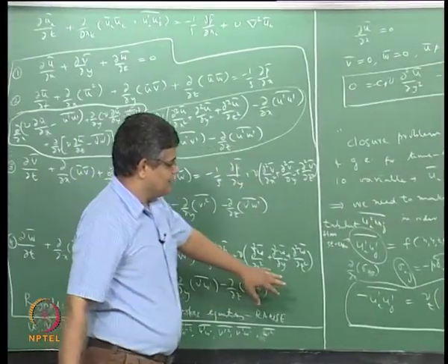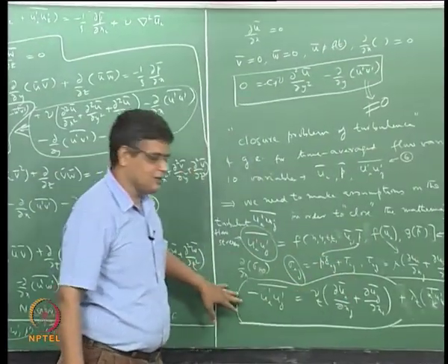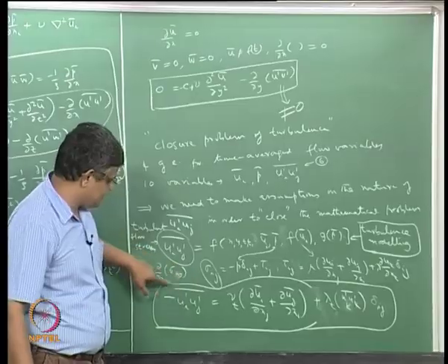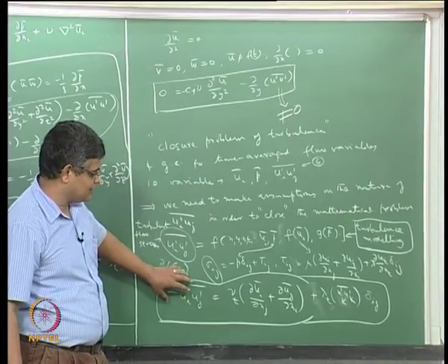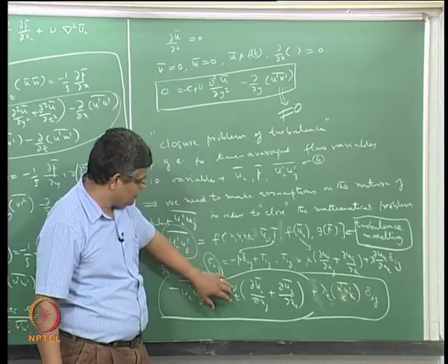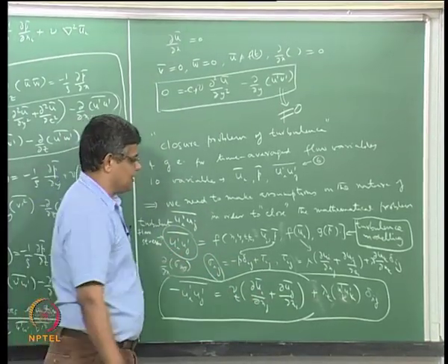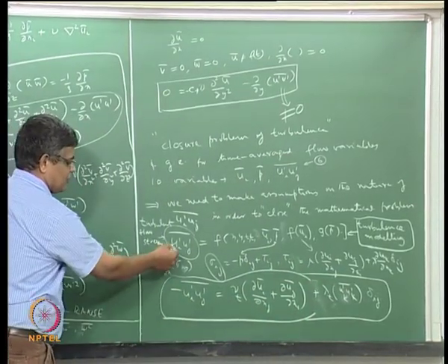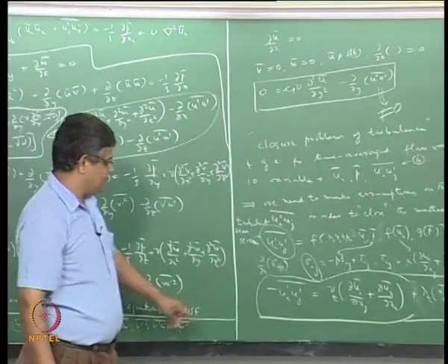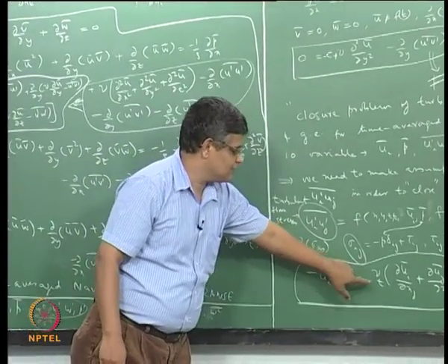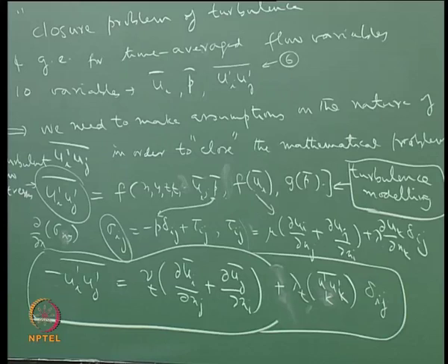So we can write it in an expression which is analogous to this, and thereby we can see that these things are considered as additional momentum fluxes which are arising out of a turbulent viscosity, and in this sense this can be called turbulent stresses, and we note that it is a minus of this particular quantity which is equated to the turbulent viscosity.